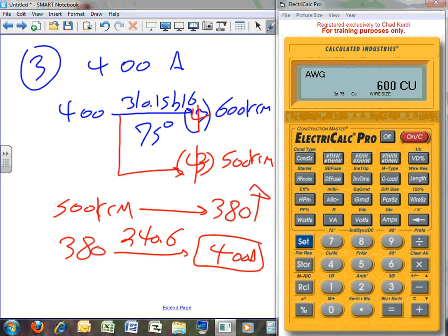Any question, guys? Any question about that? So these are four conductors. We're not derating yet. Four conductors, we're not derating. 310.15(B)(16). Any question about that? So on the test, which way are you going to do it? You're going to do it the top way, the blue. Can I do the bottom? If you do the bottom and you tell me the code says up to 800 amps, your conductor can be slightly less than the amps of the overcurrent protection device ahead of it, you're okay.